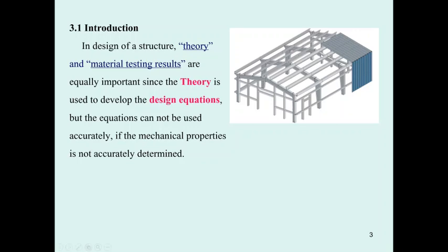W you calculate, for example, 10 kilonewton per meter, and the length may be 4 meter. And if you get the section when you design this beam, you know the I. So the equation, you need to know the E. So what is the E? The E is the modulus of elasticity of this steel material.